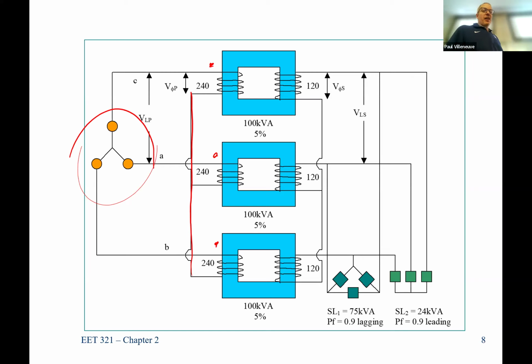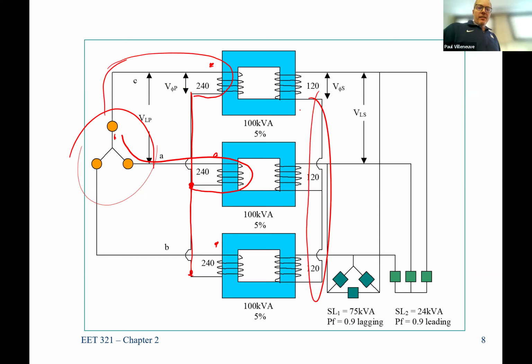So we take the 3 incoming windings, the dotted ends, and we run those to our power supply. And then the non-dotted ends, we connect together. The reason we need this is because we need to make sure that current can somehow flow out of here and then return back to here. If I connect all these to the same location, the return current can go back through and go in that direction. And it's because you have the same connection on the secondary side.